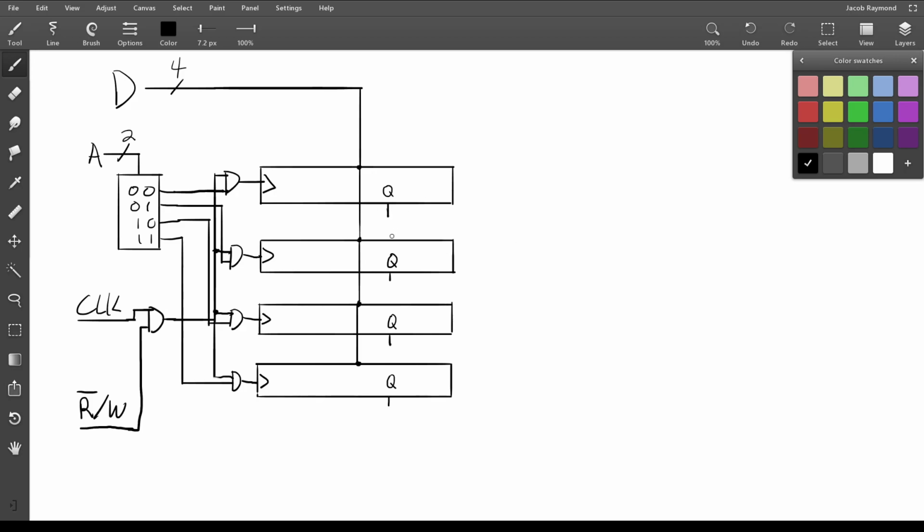So the issue, however, is that we actually have multiple outputs here. We don't just have 4 bits, we have 4 4-bit numbers. And so we actually need multiple multiplexers to be able to choose between the correct bits of everything. And so we'll just consider now, let's say, the Q3 output for all of these. So the largest bit.